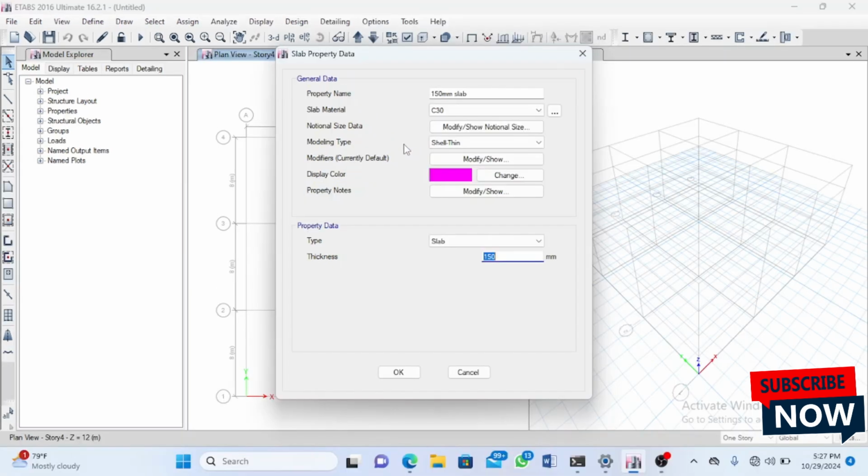And now we have our modeling type. So with the modeling type, there's one thing we also have to take into consideration. It's a very important thing we need to change. So we have various options here as the shell thin, shell thick, and also membrane and layer 2. So I'm going to explain each and every one of these, and I'm going to show you which one you are supposed to use for defining your slab. So first of all is the shell thin.